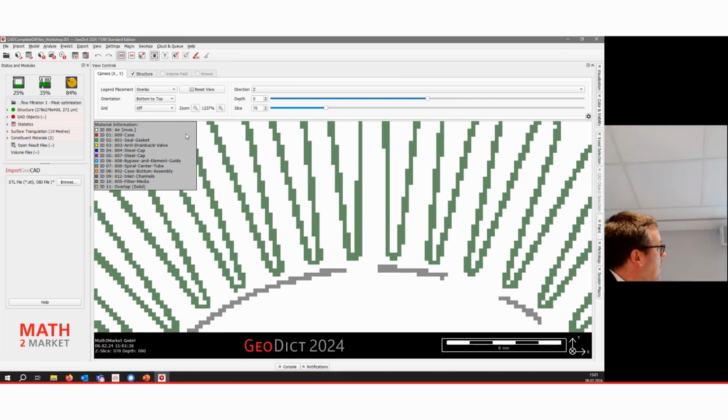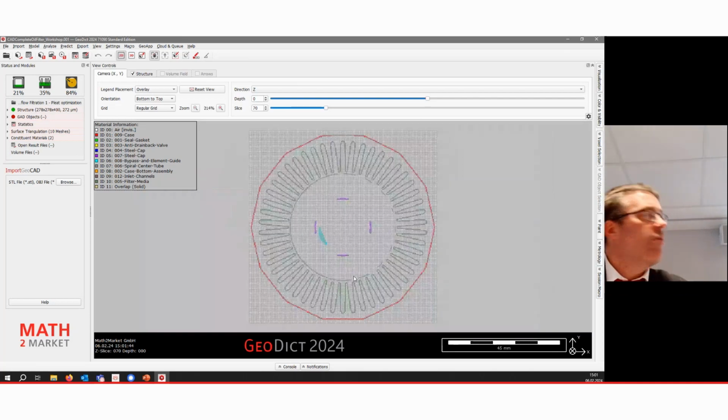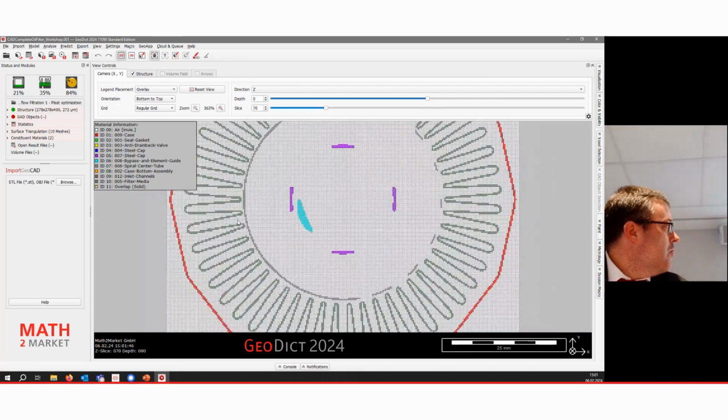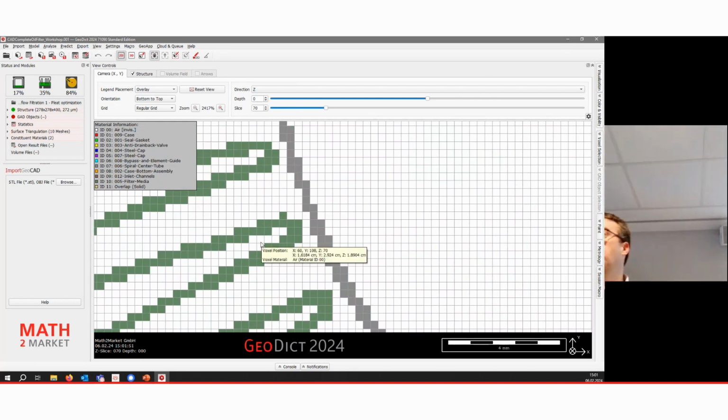And now if I zoom in that close, I can also enter the gridding here and see the regular grid. That just won't make sense if I zoom out, you would just see gray scale. But if I zoom in again, you can see in this case there's just one voxel layer. As you asked previously, maybe this one here is a bit too coarsely sampled.